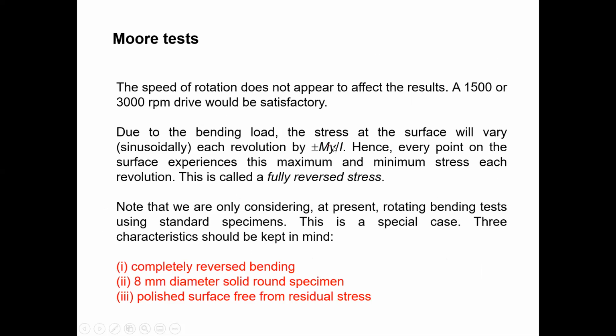So this is the bending moment equation. I think you know this equation: sigma divided by y equals M divided by I. M is the bending moment, I is the second moment of inertia, y is the distance to that point, and sigma is the stress. When you want to find the stress, you can rearrange it to this side, and this is the equation. This is what I explained.